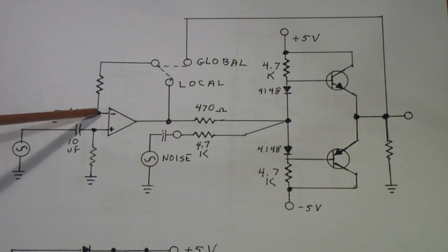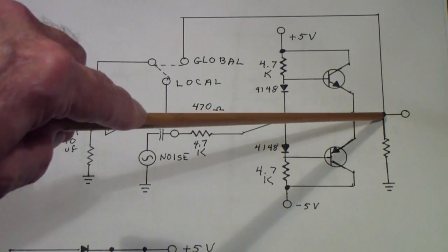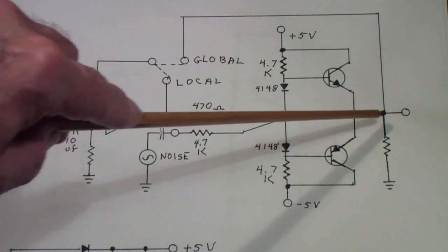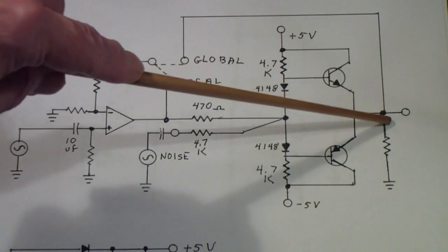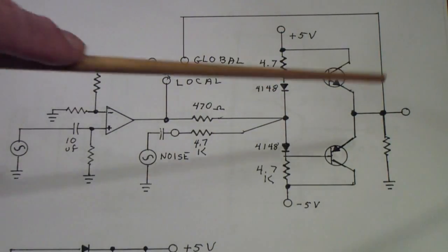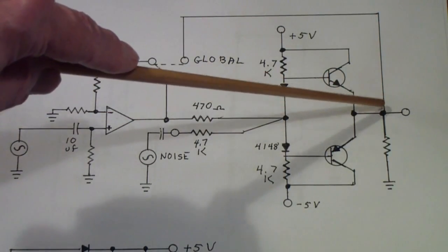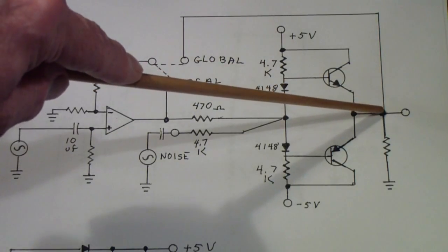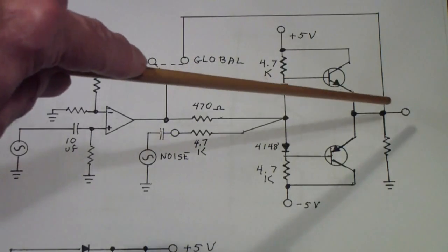It's a simple resistive voltage divider. So in this case, what we are doing is sensing the voltage at this point. And this is what is known as node feedback or node sampling. There are essentially two ways to sense the output. One is node sampling, which senses a voltage. The other is loop sampling, which we'll talk about in a minute, which senses current.